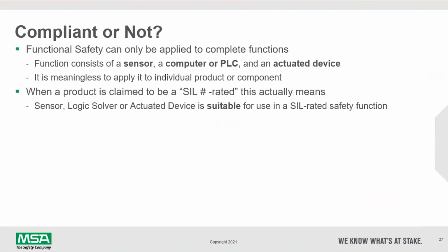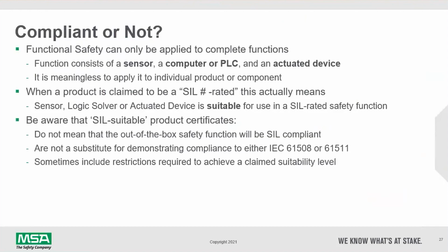And this next sentence kind of characterizes that. When a product is claimed to be SIL whatever rated, what this means is that the device is suitable for use in a SIL rated function. And it is necessary to go through the steps that John discussed earlier to ascertain, again, we're as strong as our weakest link, is our SIF, safety instrumented function, compliant to our design goal.